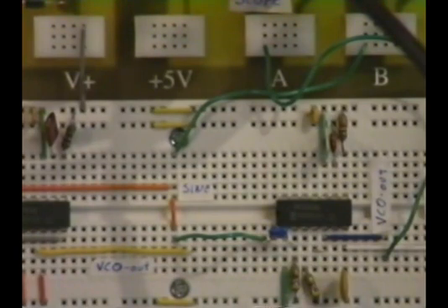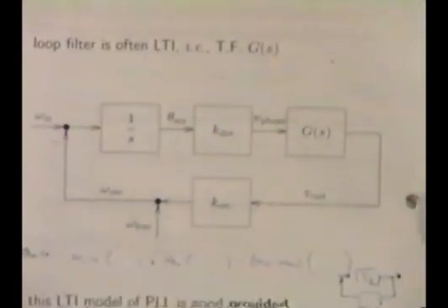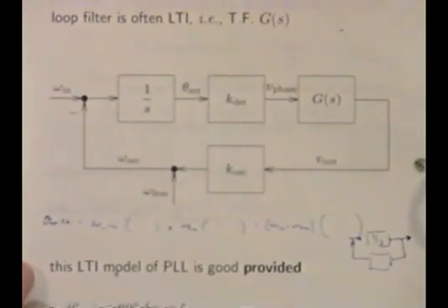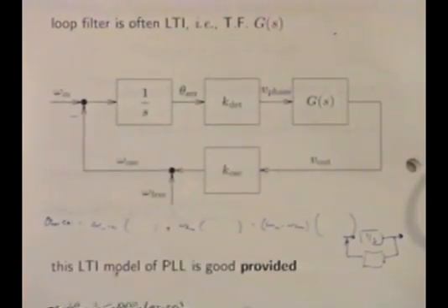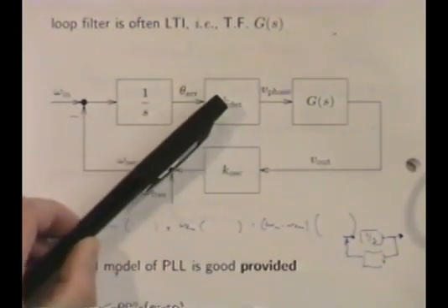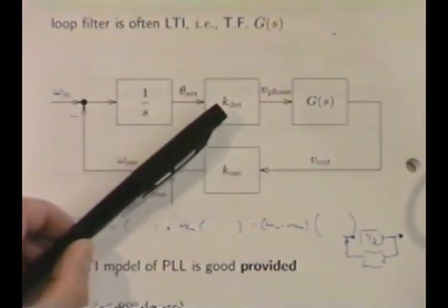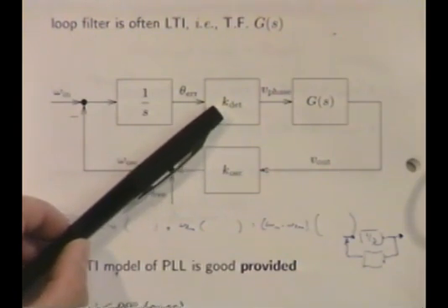Let me go back to the figure here. I'm sorry about this, but maybe if you could just pan over here, and there you go. Okay, so here's our PLL figure. We have an oscillator hooked up here to provide our input frequency. We'll see that in just a minute on the oscilloscope. This little integrated circuit contains a phase detector, which is quite like the phase detector in the notes.